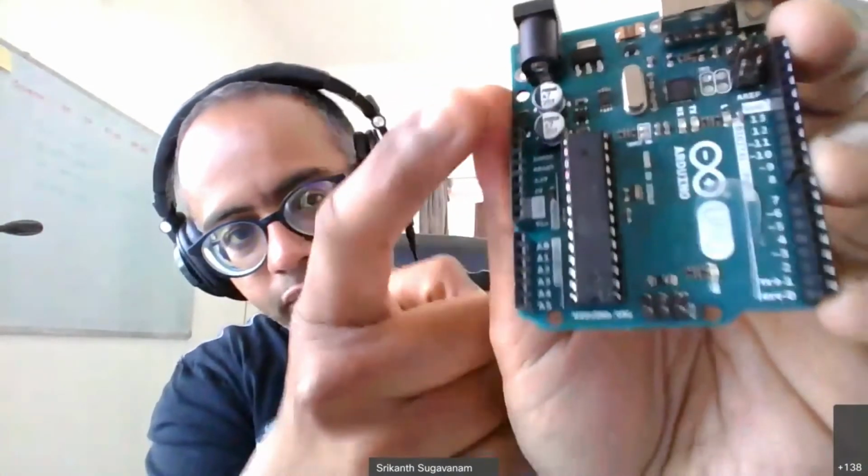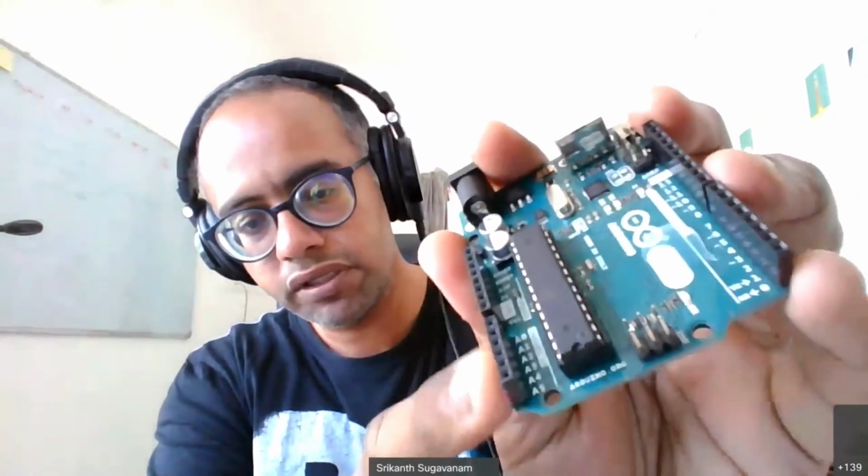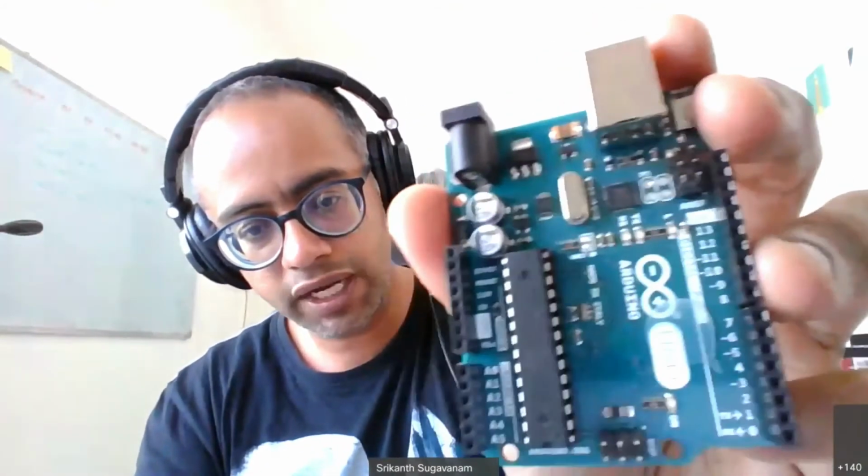Now if you look at it, there are several pins here. And amongst those pins, you have the voltage pins because you have to supply power to it. And also you can get power out of it, which means that you've got a 3.3 volt DC supply, and you also have a 5 volt DC supply on one of these rails. So you can take a wire from here and plug it to a sensor or any other device you want to power. So you can power devices from this. It has analog input pins here, and it has got digital input and output pins here. So you can generate both analog inputs and outputs using this device.